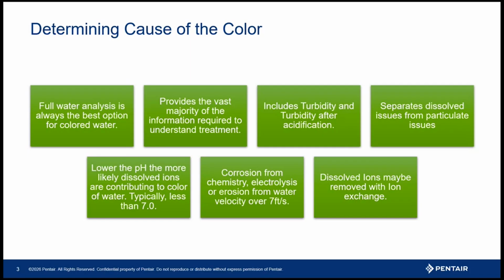Now, how do you determine turbidity in the field? Well, you can invest in a turbidimeter if it's really in your wheelhouse. That's one of these devices up here. There is a LaMotte chemical turbidity test that suspends particulate out, and you can judge it from a color indicator, or there's something like this field photometer that, besides doing chemistry, will take turbidity units in the field.